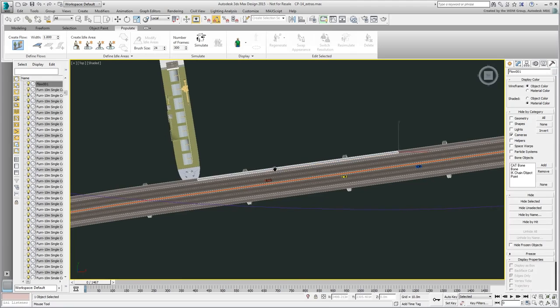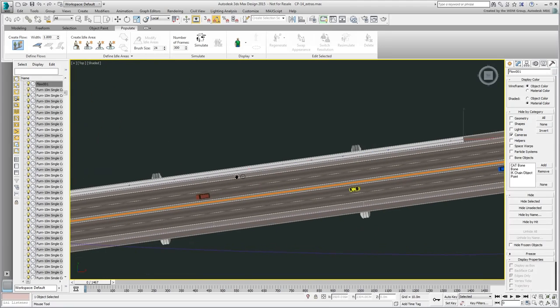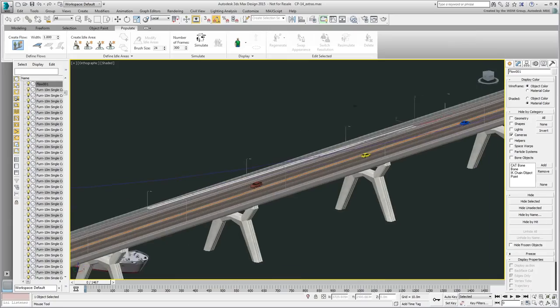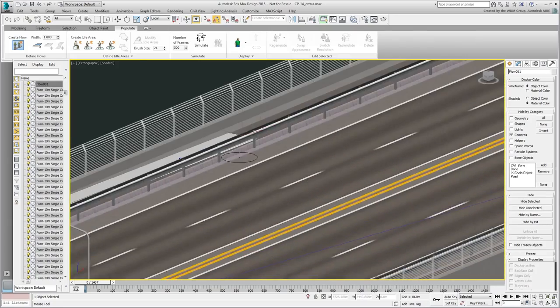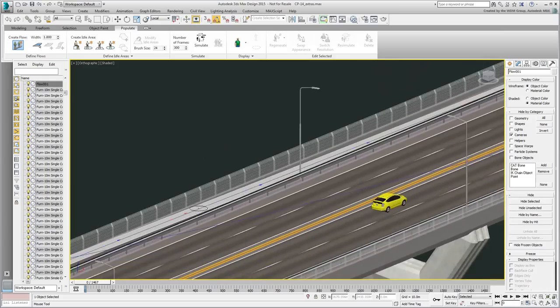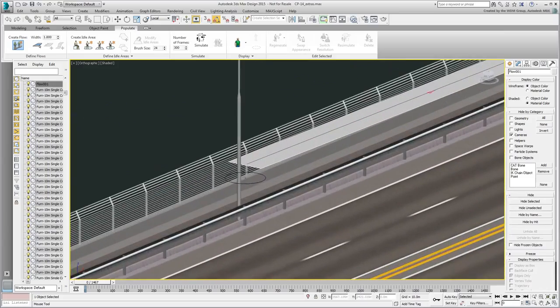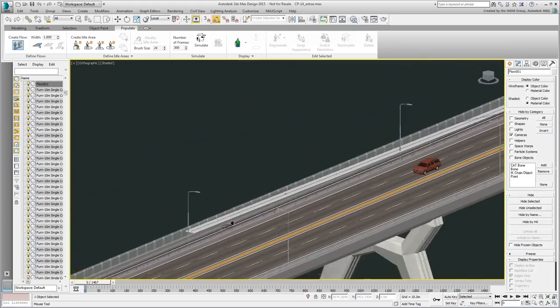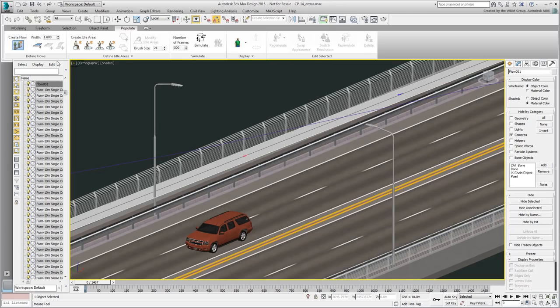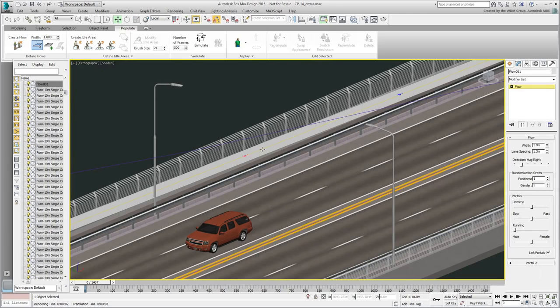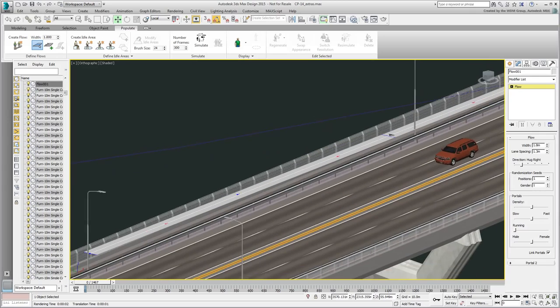This may look fine in the top view, but try looking at it in a 3D view and you'll see the problem. The starting point looks okay, but the ending point is too high. In this case, you'd need to edit the flow by selecting the midline and adding a ramp to it. Now the flow is divided in 3 parts.